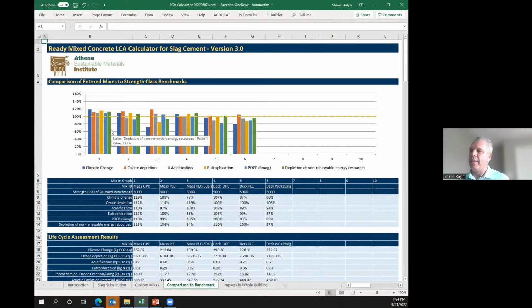And when we look at cement aspects, when it comes to EPDs, right now, most of the impacts in concrete are going to be influenced by the cement going into it. Even though cement might only be 10 to 15% of the total weight of the ingredients in concrete, right now, because of the energy intensiveness of making Portland cement, 75 to 85% of the impacts in concrete can be adjusted.